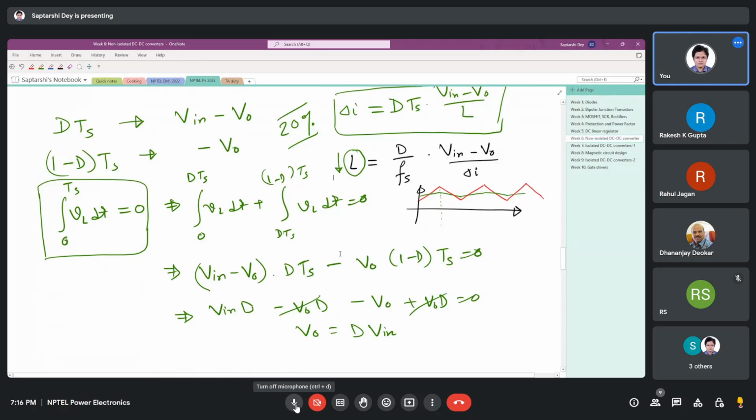One of them is that the circuit becomes very small. Keeping everything else constant, if I increase the frequency I can reduce the inductance without affecting the performance, ideally speaking. So if I have a smaller inductor, my whole circuit footprint becomes smaller.